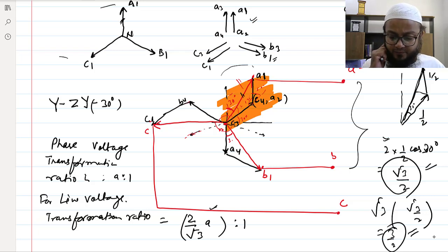So for all these kinds of connections in the 3-phase transformer, we have talked about star-star connection, star-delta connection, delta-star connection, and delta-delta connection. And in delta-delta connections, we have seen the open phase, the V connection, the open delta connection. Then we have talked about Scott connection and zigzag connection. So these are different combinations possible. Basically, we should know where to use which kind of connections.